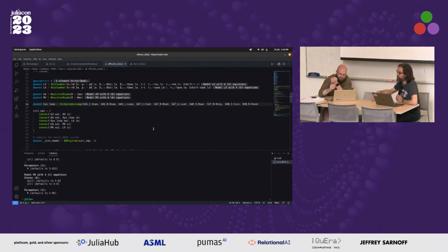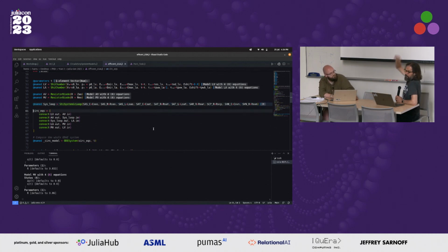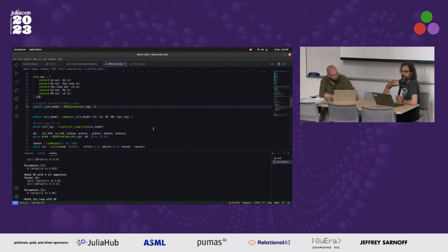And you can do similar things with the parameters. I don't need to change parameter number 45, which, I have no idea what it is, but I want to change the resistance in the capillaries. I have no idea what the order of my parameter vector is and what the resistance of the capillaries is in that vector. But ModelingToolkit has cleverly, for that reason, introduced parameters not the way we have it now with a parameter list and global variables, but as a parameter map.